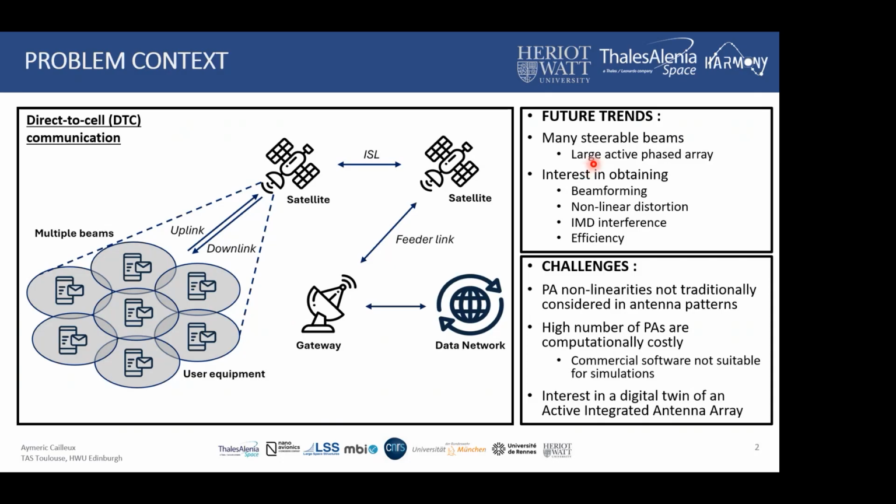And then we are interested in obtaining the beamforming, but also the nonlinear distortion, the IMD interferences from this system. And also, as we have a large number of power amplifiers, we are interested in the efficiency of the full system. Nevertheless, such a technology will raise some challenges.